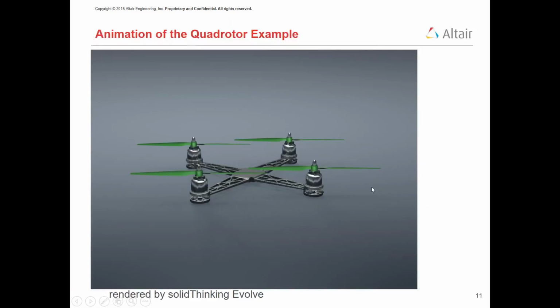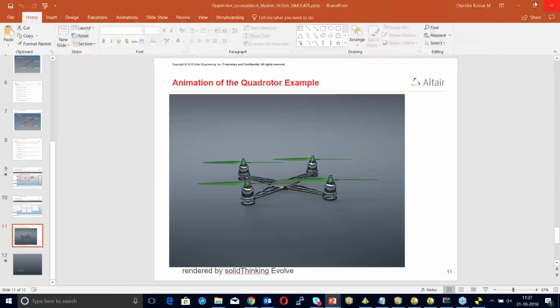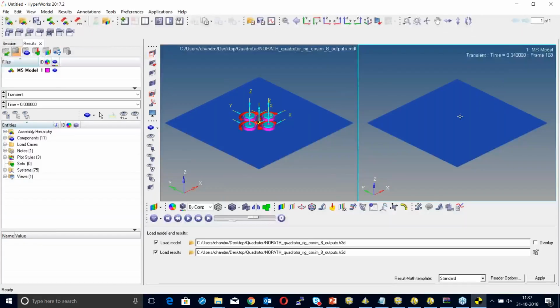So now apart from this, it's not only that we have done the MotionSolve coupled with Activate, but we have done the entire design and implemented it. During our ATC, we showed the physical drone flying up. The structural part is taken care of with Altair Inspire Motion. Then we have done the FEM analysis and the weight optimization. And then later we did the MotionSolve and Activate coupling to do the entire system simulation to virtually validate it.